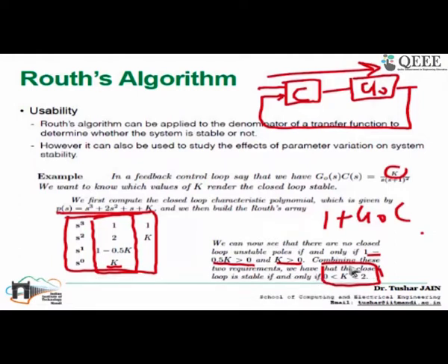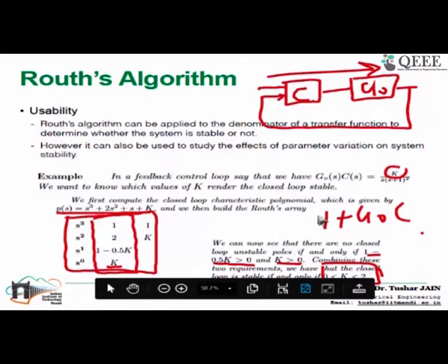So here in fact, there is an interesting point. While determining the stability of the system, you actually computed the controller that could give you a stable closed loop. Okay, determining the stability is one step, constructing the controller is another step, but within the one step only you have analyzed the stability and you have constructed the controller.